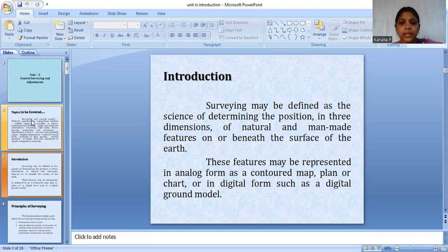Geodetic surveying, which is called trigonometrical leveling, deals with long distances and large areas. The curvature of the Earth is taken into account, considering the Earth as a perfect sphere. The line joining any two points on the surface of the Earth is curved and forms an arc of a circle. The figure formed by the lines connecting any three points on the mean surface of the Earth is called a spherical triangle.